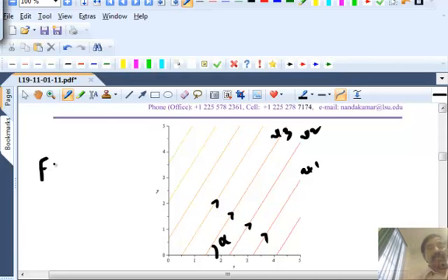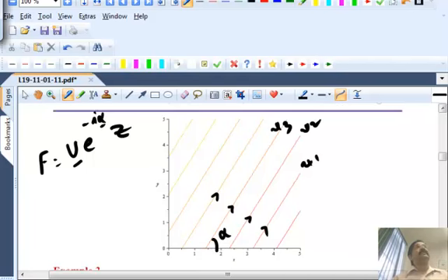So you are given that f is equal to u e to the power minus i alpha z, and asked for what potential flow geometry is that a solution? And the answer is, it is a free stream velocity with a constant velocity u and a constant angle alpha to the x-axis. Okay? Any questions on that?